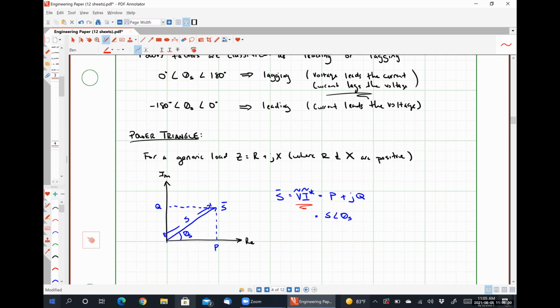Because you all use calculators. And you can choose whether the results of your calculators are given to you in rectangular form, which then inherently gives you average power and reactive power, or in polar form, which inherently gives you the apparent power and the power factor angle, okay? So you do not need to memorize all those equations by any shape or form. You just need to understand the relationships, which is conveniently summarized in this simple triangle.